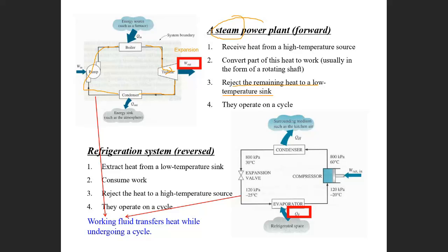For the reversed heat engine, for us to better understand, think of our home refrigerator and air conditioner. We extract heat from a low temperature source, and then reject heat to a high temperature sink.